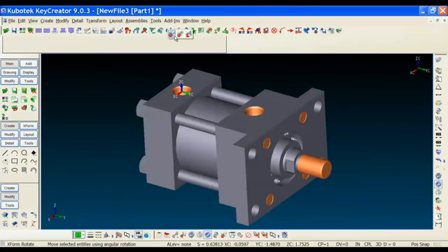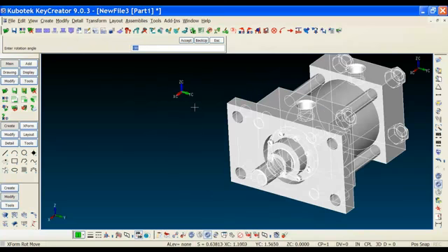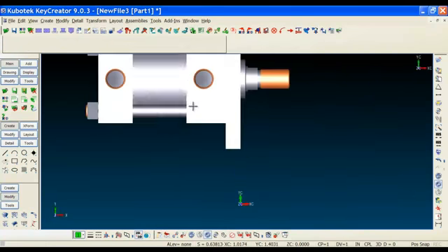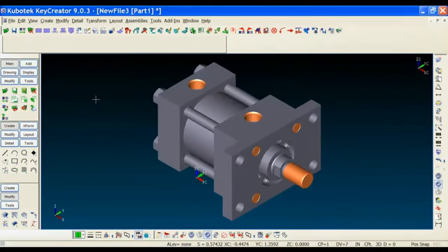So the first thing I need to do is put this geometry on level 7. The isometric view, or the 3D geometry, goes on level 7. So after it's put on level 7, I have to establish the major axis, or the installation direction of the component. So the action of this component is always in the movement of the rod, and it's installed in that direction as well. So we have to put that in the world X direction.